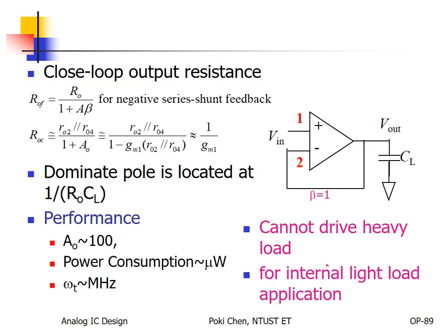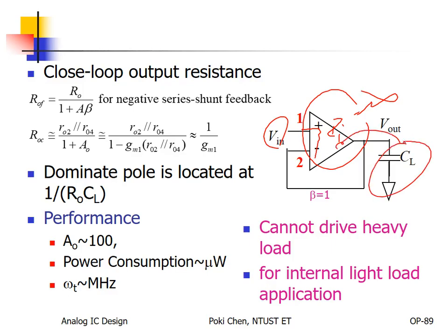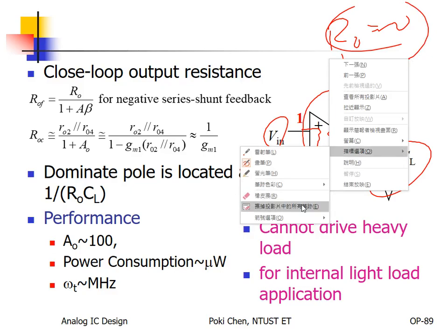On chip, actually, there are some interesting applications for op-amp. For example, I talked again and again about such kind of voltage driver instead of current driver. So what is the most important characteristics for such kind of voltage buffer? To get 100% of the input voltage, actually we hope the input resistance hopefully should be infinite. And hopefully we can drive all the output voltage to our load. So we hope RO should be 0. That is we discussed in last week.